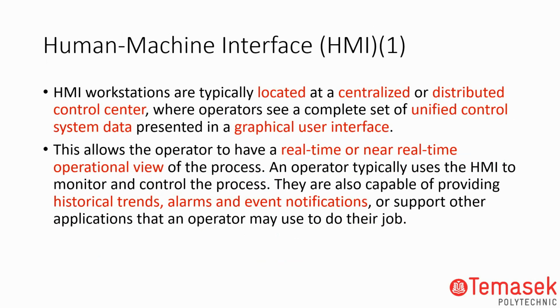Next, HMI. HMI is located in centralized distributed controls. You can see the GUI, and the operator would have real-time or near real-time operational usage when you're running it. When you're using HMI, you want to monitor the process, you want to control and look at the historical trend, you want to look at whether there are alarm or event notifications.